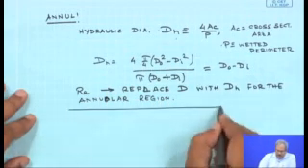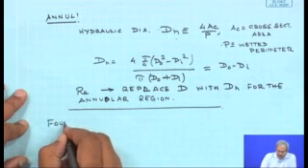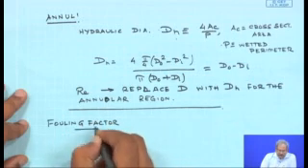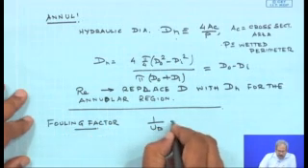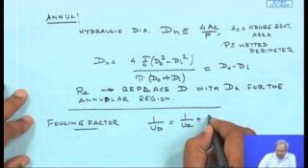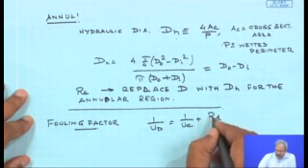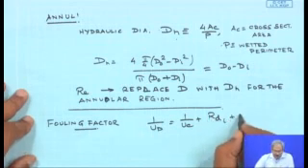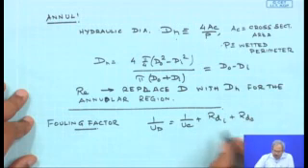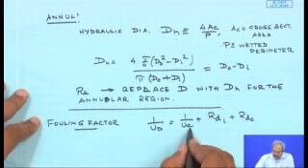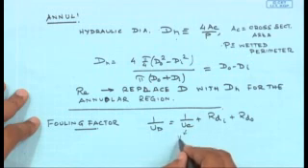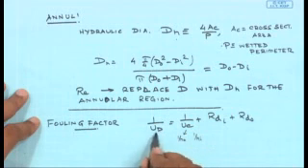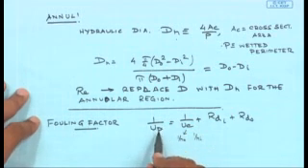And you take care of the fouling factors as before. When you have fouling present, 1 by UD is 1 by UC plus RD, the fouling factor at the inside plus RD at the outside. So, this is the clean coefficient which depends on HO and HI. This UD is the coefficient while the double pipe heat exchanger is in operation.